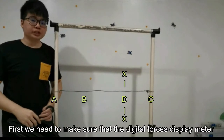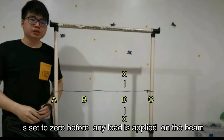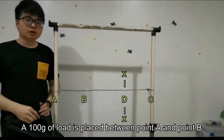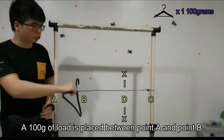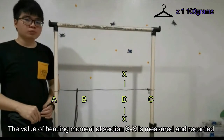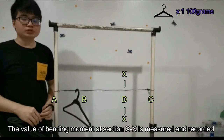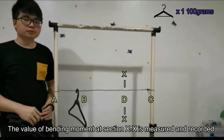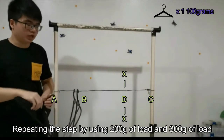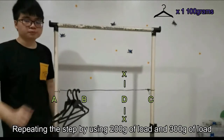First, we need to make sure that the digital force display meter is set to 0 before any load is applied on the beam. 100 grams of load is placed between point A and point B. The value of bending moment at section XX is measured and recorded. Repeat the step by using 200 grams of load and 300 grams of load.